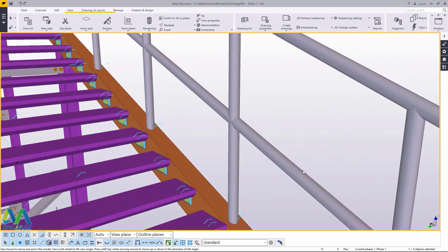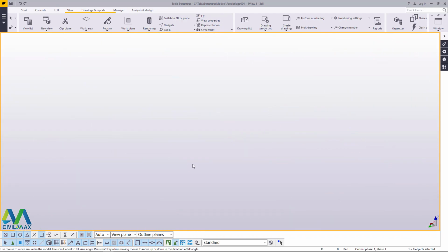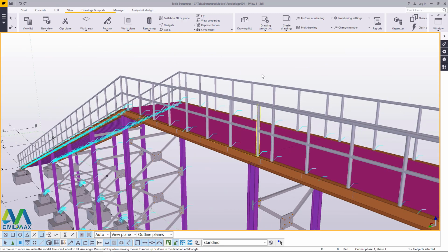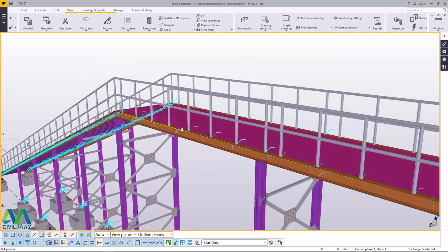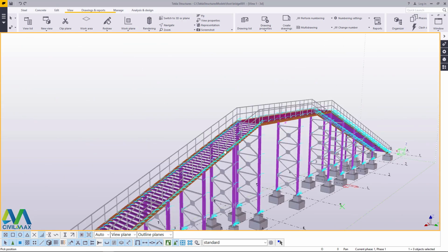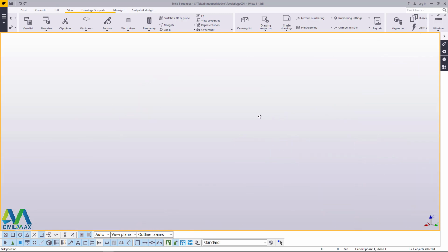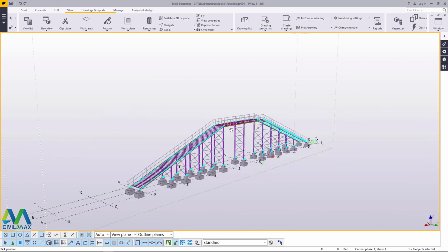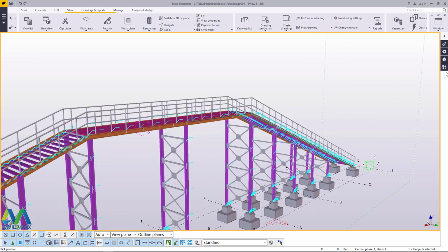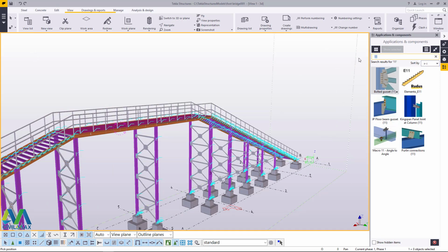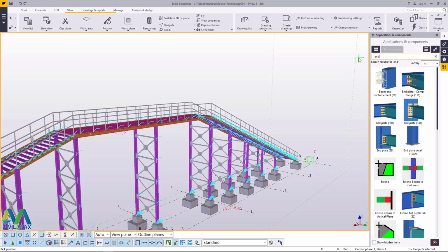Now on the treads, we can use timber or checker plates, whichever works best for you. So this connection at the far end here shouldn't be something that takes you so much. You can come here and double click here and just type end plates, but I'm not doing that because I'm taking care of time, because I don't want to spend so much time connecting these individual columns to the stringers and the walkway.